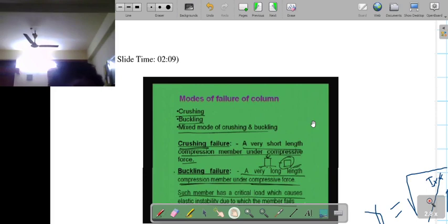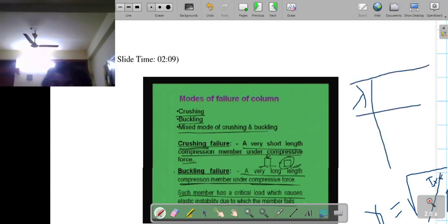The other way of finding this is in the code book, in table number 5.1, given in clause number 5.5. In the code book, a table is given to find the sigma SC value. This table is based on the values of lambda and the values of Fy. Lambda is given in the vertical column, and the defined Fy values are given across, starting from 240, then 250 and so on. Since IS 800 1984 still recommends using Fy 250, we will concentrate only on Fy 250.